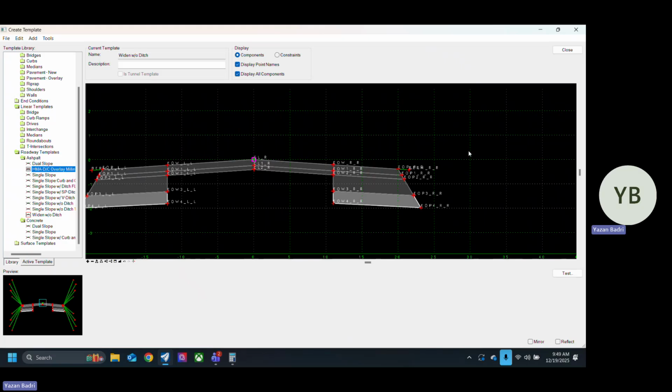In our pavement section, we're gonna do prime coat and tack or whatever. Do you recommend putting the line in there and then using that for your quantities? How do you do that typically? Personally, I don't model it. It's just too small of a layer.